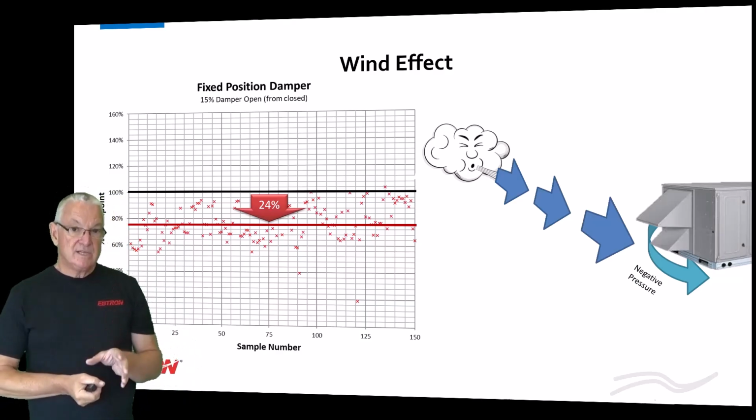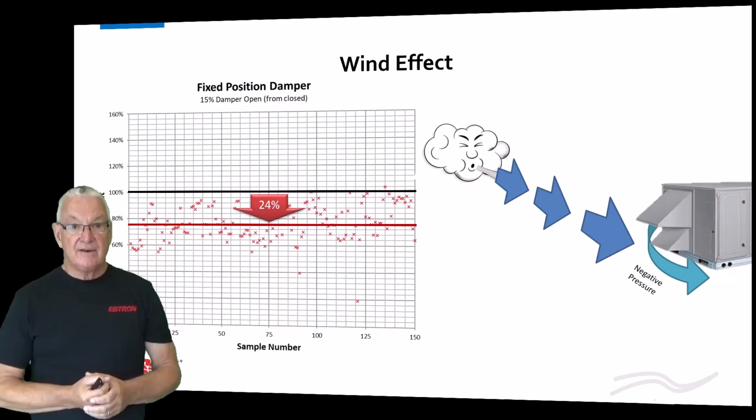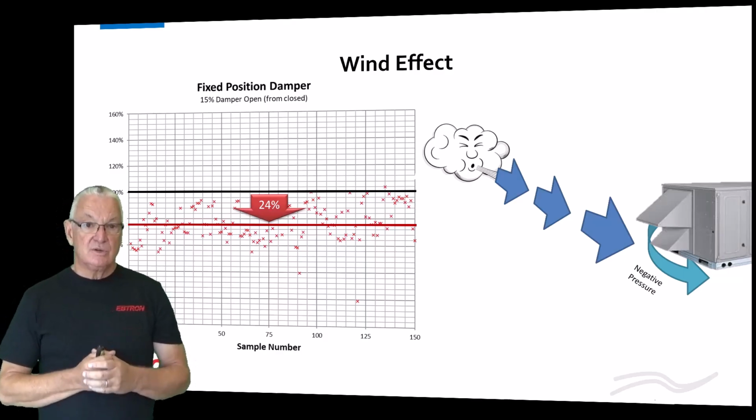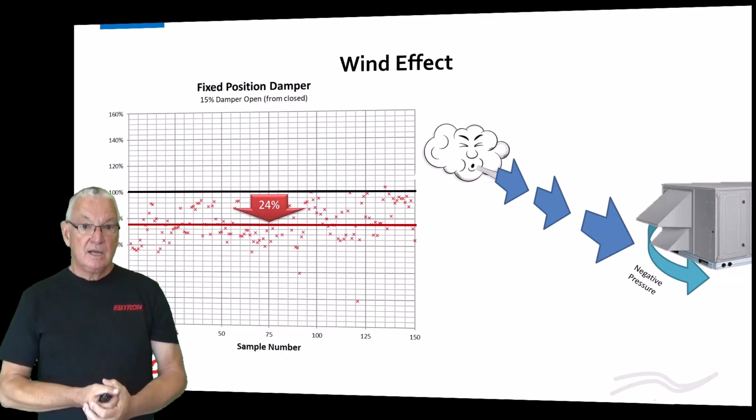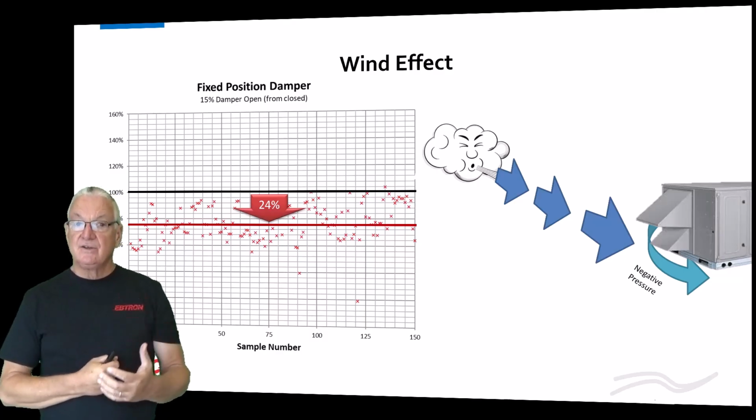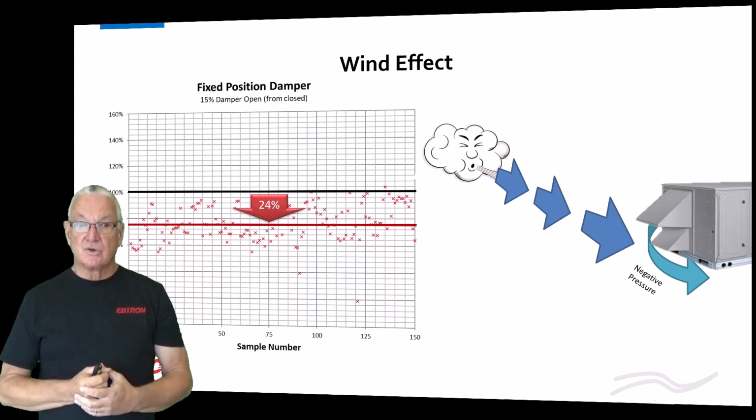One of the problems we see a lot of control folks create is that they have the output of their control loops too aggressive, too fast, and it'll actually make the system hunt. You have to really understand how to do this. Slow down the output of your control loops.